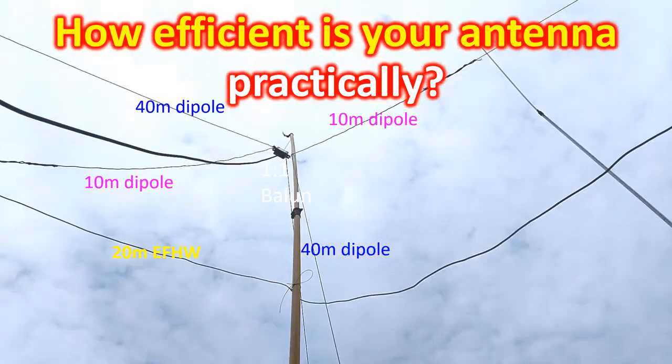Important parameters of an antenna are the gain, directivity, radiation pattern including the angle of radiation and polarization, beam width and effective aperture. All these will determine the efficiency of the antenna for a given application. Gain of an antenna is usually mentioned in comparison with the gain of a theoretical isotropic antenna (dBi) with spherical radiation pattern all around, or sometimes in comparison with a dipole antenna (dBd).